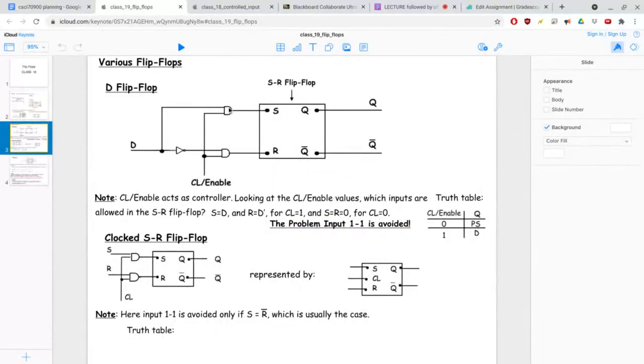Then we now plug the clock into it, and we say that this flip-flop is only going to change when the clock is on, right? At every other moment when the clock is not on, not enabled, the flip-flop gate will not change. So the Q will remain the same. So we can say interchangeably the value of the flip-flop or the Q, right? We're talking about the same thing. Q is the value. Okay.